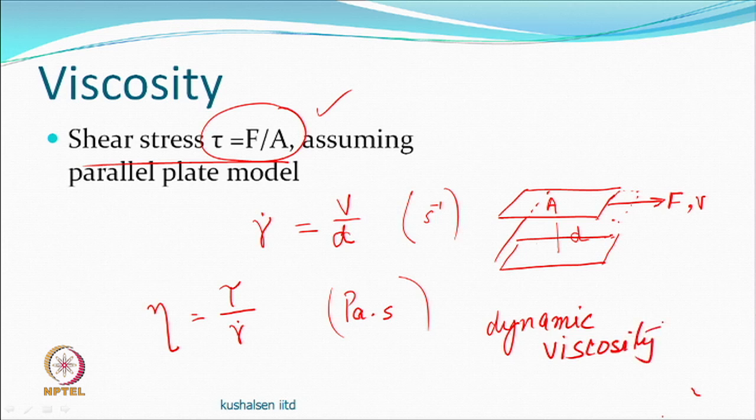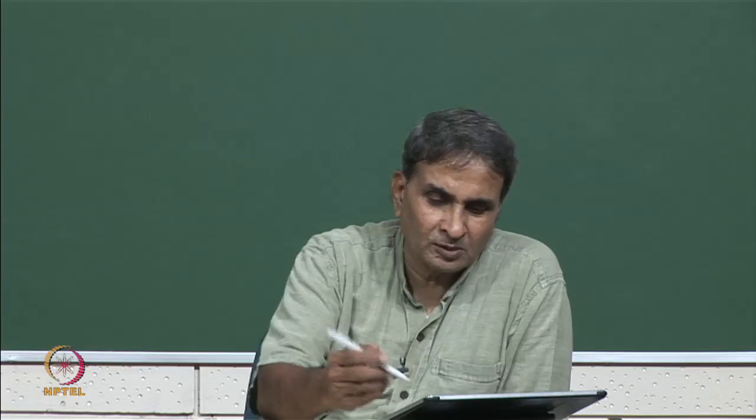Because if nothing is moving, you do not know how to measure viscosity. They must move relative to each other, you see. Unless there is a motion, there is nothing. Even if you put a ball in a polymer solution, it will go down, but it must go down. If it just stays there with zero velocity, there is no change, all right. So, there is a relative motion. Now, this relative motion means there are molecules. In the case of polymer, there are long chain molecules. They can be branched based on their length. They can entangle more and therefore offer more resistance, and therefore this force would keep changing. You have to apply more force to move, and therefore you would have more viscosity, and that is how people believe.